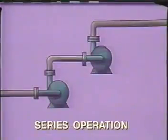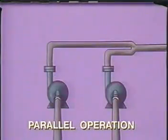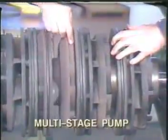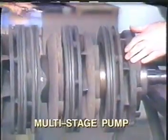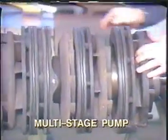When pumps are operated in series, the discharge of the first pump provides the suction for the second. This arrangement is used to increase the pressure over that of a single pump. They may also be set up in parallel where both pumps have a common discharge. This arrangement is used when an increase in volume is required. A multi-stage pump may be used when higher discharge pressures are required. This pump is like several single-stage pumps operated in series, but the impellers are mounted on a common shaft and enclosed in one casing.